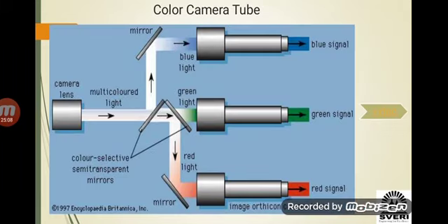Now whatever image you have seen is for black and white, because in a composite video signal we see the amplitude of the signal varies continuously. It indicates values of gray for a black and white television, where the highest value will be white and the lowest value will be black. So its value varies from 0 to maximum, from black to white.